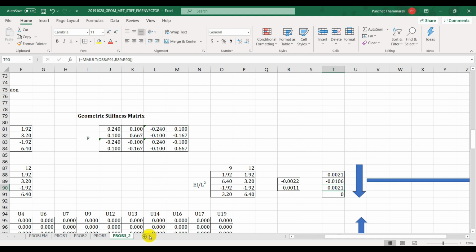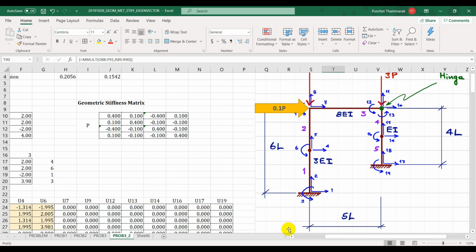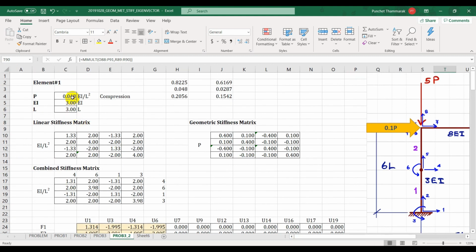So basically we can put the conclusion in here that if the P magnitude is 0.05, this is the applied P, okay? But the final axial force in the column was corrected. So that's another thing. But we put the applied P in here. You say that in the column you don't see the 0.05, you get 0.048.